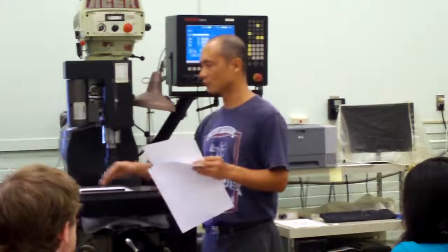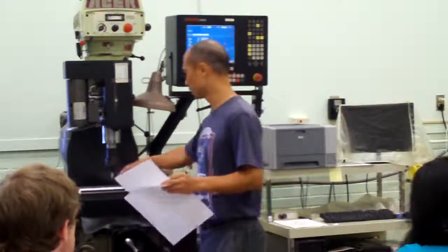Because circular motion actually involves reversal. Last time when we went through the drawing, I asked you to notice the motion of each axis. They have forward and backwards, therefore they involve some acceleration and deceleration. The difficult part of CNC machining is those very small circles, arcs, with very small radius. If you try to run the arc at very high speed, you tend to generate error because of the acceleration of those individual axes.